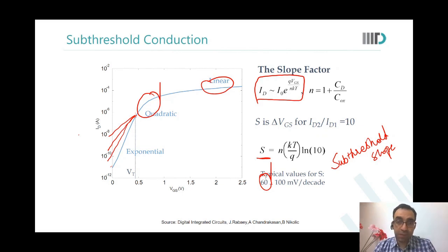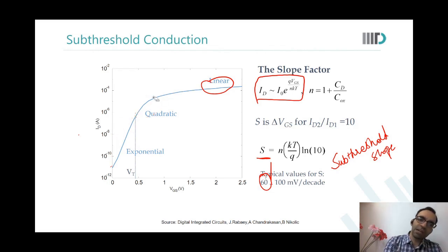Yeah. So leakage is a very major issue in advanced technologies. Earlier we used to think that if we reduce the VT, we would reduce the leakage, but it is not happening that way. VT reduction would always lead to an increase in leakage. What does VT reduction mean? VT reduction means that I will shift this entire curve a little more to this side.